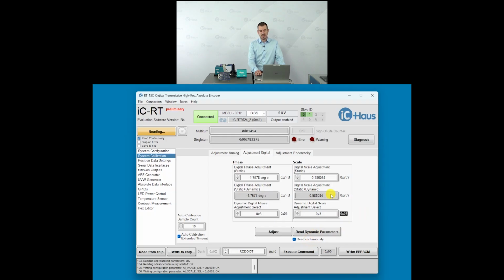And you will see in those green, gray backed boxes here that there's a little bit of flickering going on, because systems are moving, systems are not 100% stable, right? So you see the LSB here is flickering at the scale error, and same for the phase error. For the phase, the ideal position would be at 1 degree electrical here. So we're more than close enough to ideal position, but what I'd like to show you is the scale error related to the radial displacement.